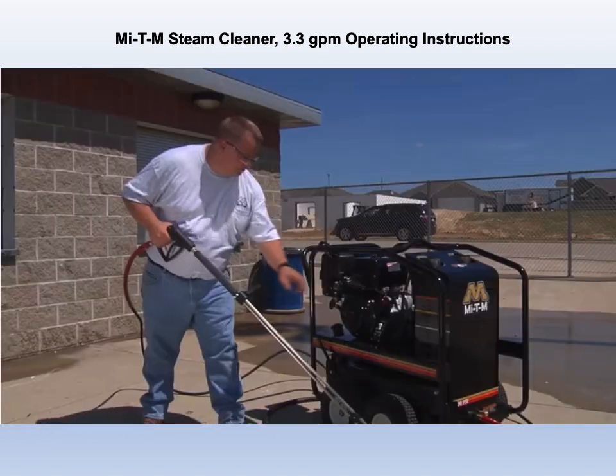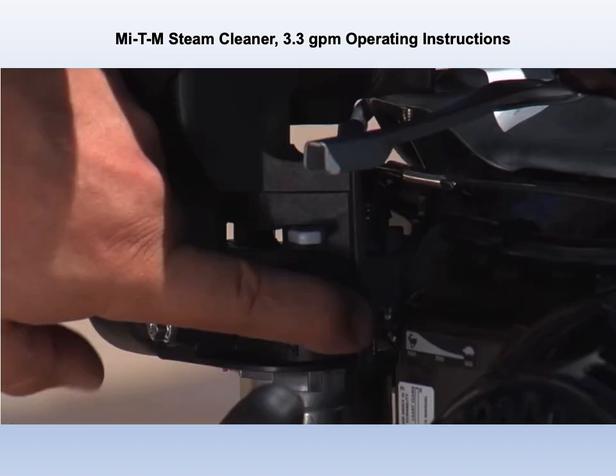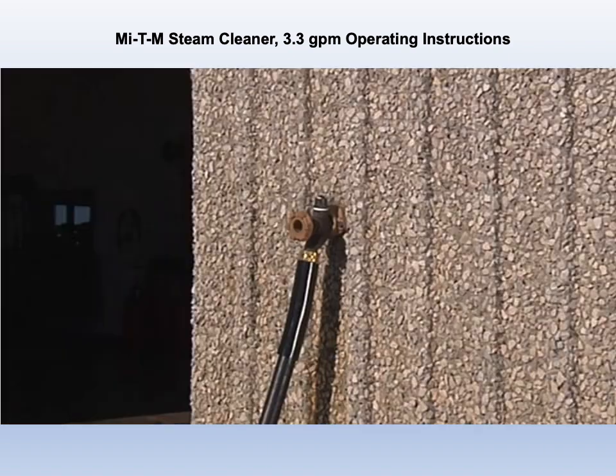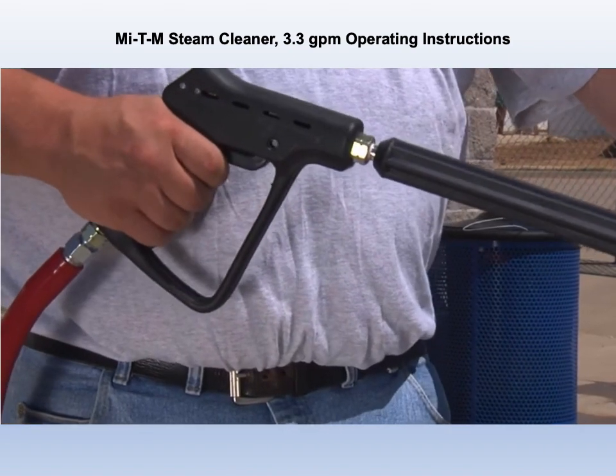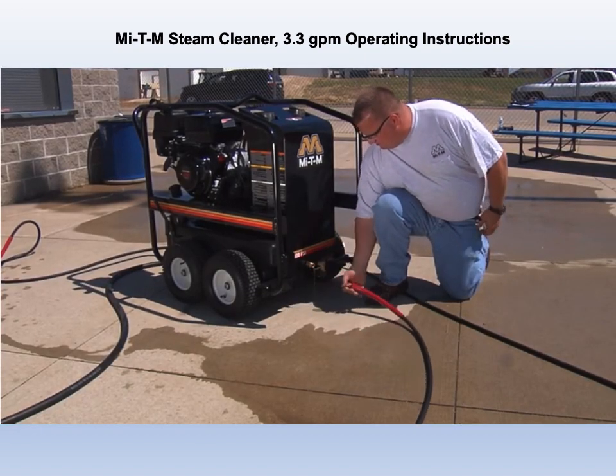Turn the engine switch to the off position. Turn the gas lever off. Turn off the water supply and pull the trigger gun to release pressure. Disconnect the high pressure hose from the unit. Disconnect the garden hose.